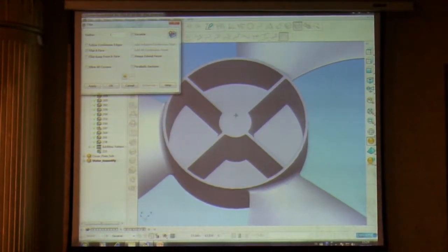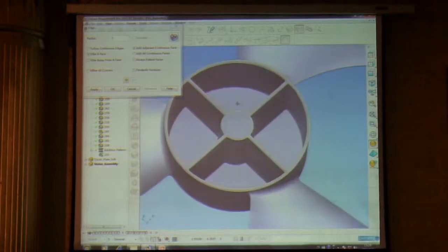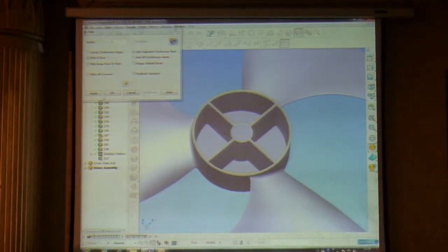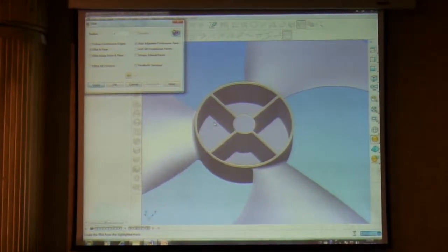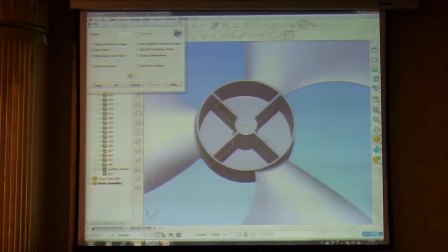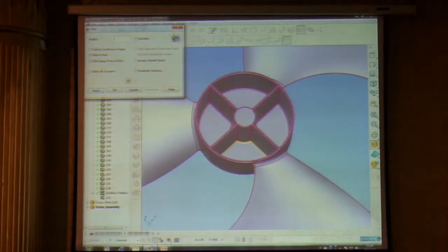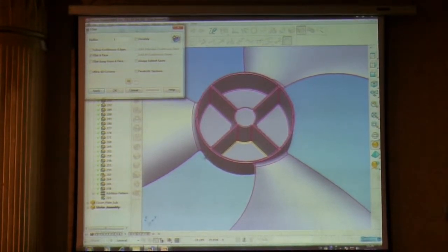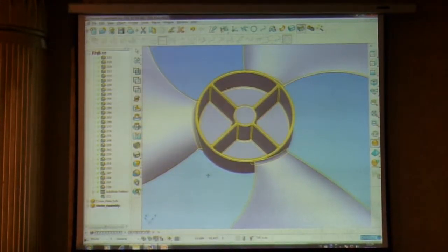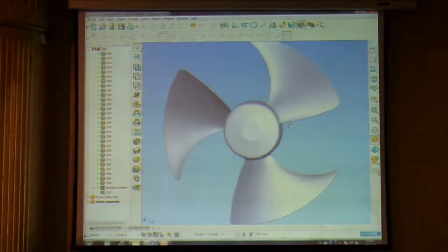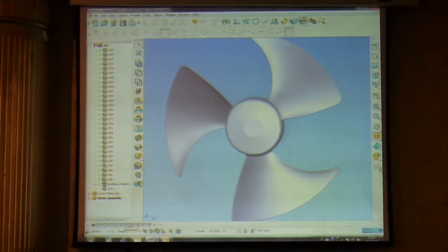Also, I can fillet all the edges of a particular face. So if I pick this face on the top, again we create 5 fillets in one go. Again, I can select multiple faces, so here 4 faces, and in 3 filleting operations we've created over 30 fillets. Okay, so my blade shape is now complete.